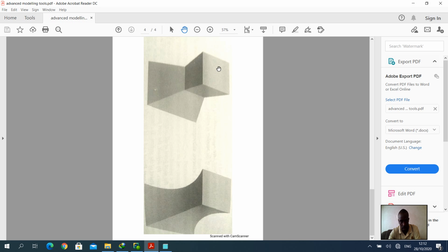Basically, this component has got three sections. It has got one, the base, which is rectangular, and I'm going to assign this rectangle the dimensions 100 by 100, and we've got the middle section, which is also rectangular in nature. I'm going to be assigning 50 by 50, and then lastly I'm going to be assigning the top section as a rectangle, which is going to be 80 by 80. So we can make this component easily using the blend operation.